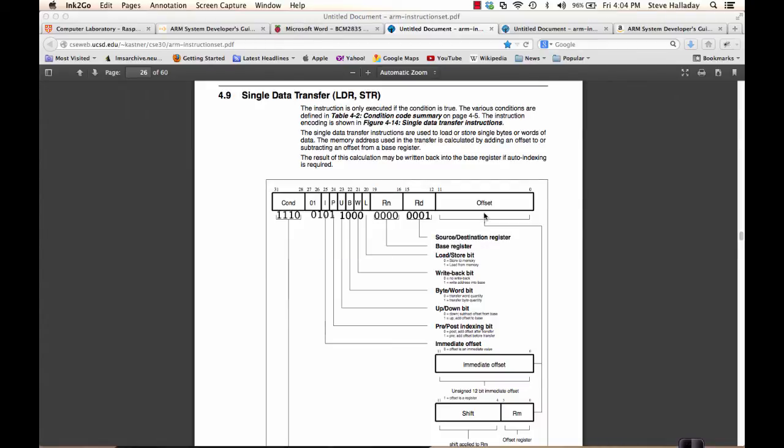And then finally, the offset, depending on which register in the GPIO controller we want to write to, it could be a value of 4 or 1C or a value of 28 hex. So for this example, we'll choose the value of 4, so it'd be 00, 00, let me put a space in there, make that a little easier to read, 04. So that's our 12 bits here.